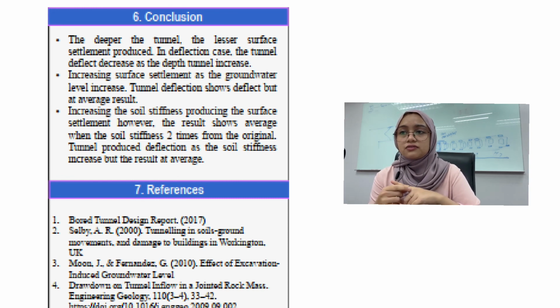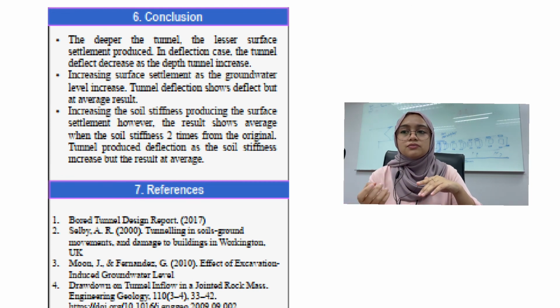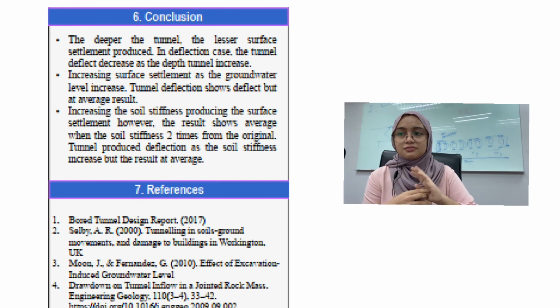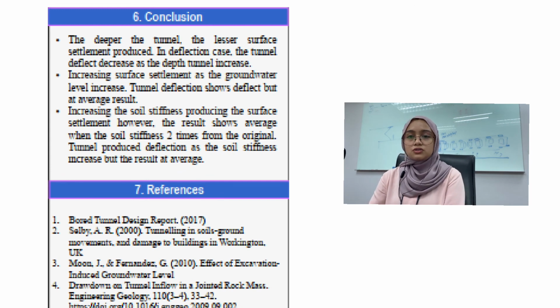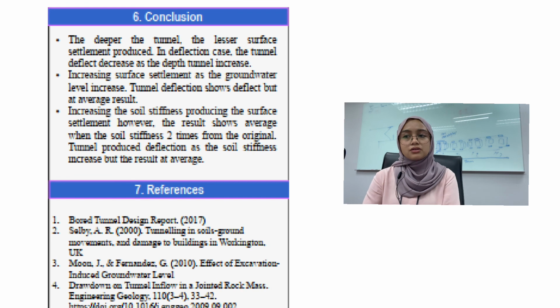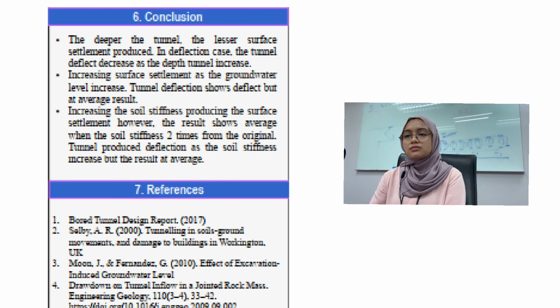After finding the cause of settlement, I built a soil model and tunnel model using the Finite Element Method to analyze the ground settlement and deformation pattern of soil based on three key parameters. Even so, this study does not represent the actual on-site case, where many considerations must be considered, such as the surcharge, soil condition and others.